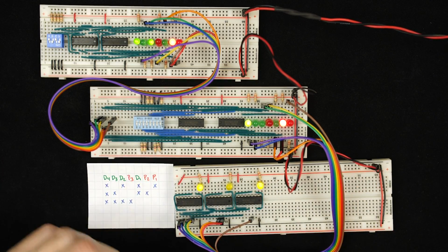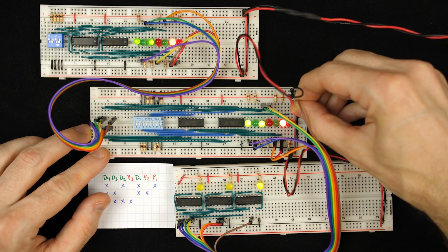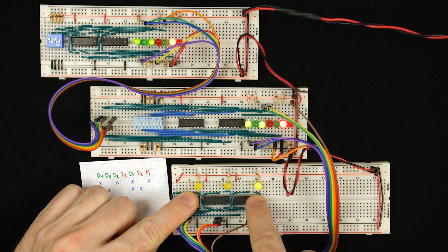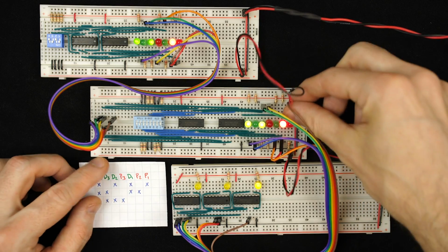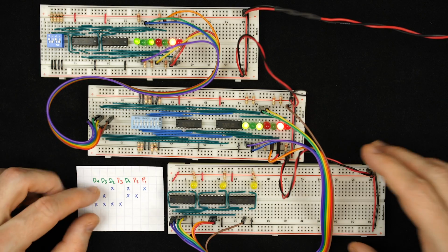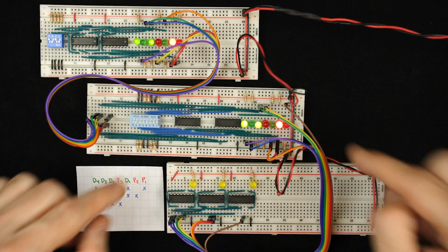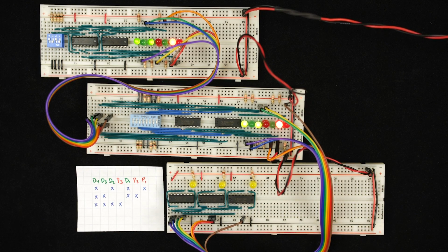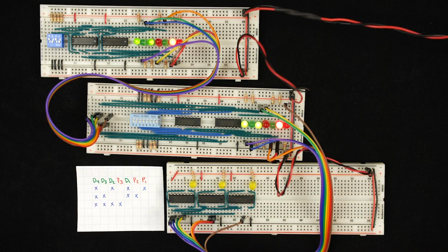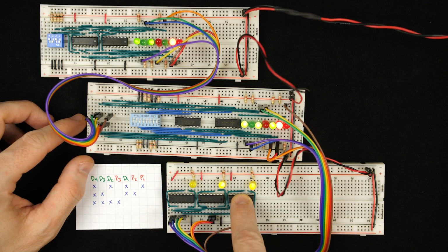And that's actually why, funny enough, when I first hooked this up, you remember I had this wire just off by 1 like that. And I immediately knew, just by looking at this, wait a minute, something's wrong with bit 1. So did I hook bit 1 wrong? And I did. I had it off by a little bit. That's the nice thing about working with error correction circuits: if you have an error in your circuit, it tells you about it. And not only that, it tells you how to correct it. So it told me that bit 1 was hooked up wrong. So there we go.